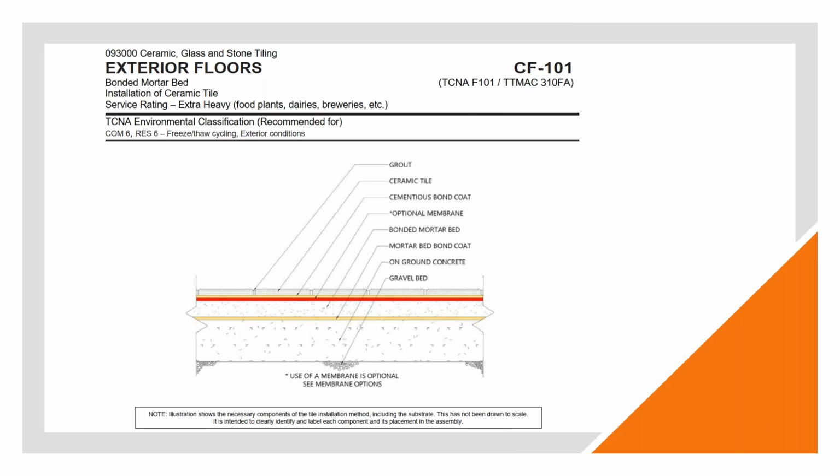A lot of times we don't know what the condition of the drainage is below the slab on grade. And that's an instance when that optional waterproofing membrane that's indicated by that red line on the drawing might be necessary, because that would stop the water intrusion from the top at that particular point, and it would never reach the slab below and would run off in a much more efficient way and leave that surface free of excess moisture.